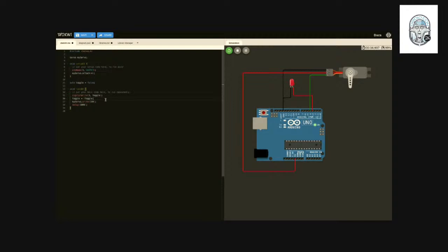Now, for servos, there's usually two styles of doing it. One is degrees and one is in microseconds, which is just the pulse value. So you'll see numbers like in the RC controller between 800 and 2500. Then that's the microsecond version. But in the servo library, they use degrees for the most part.